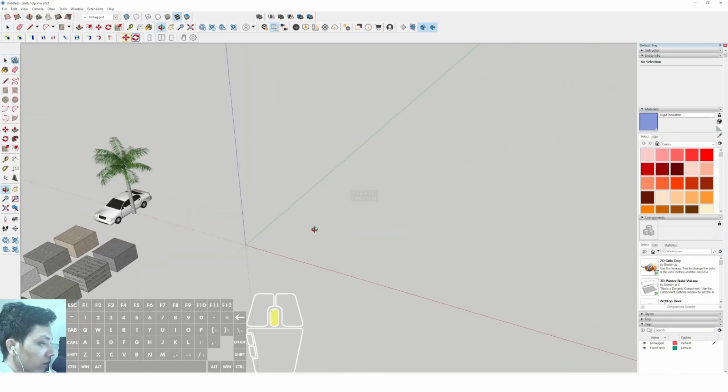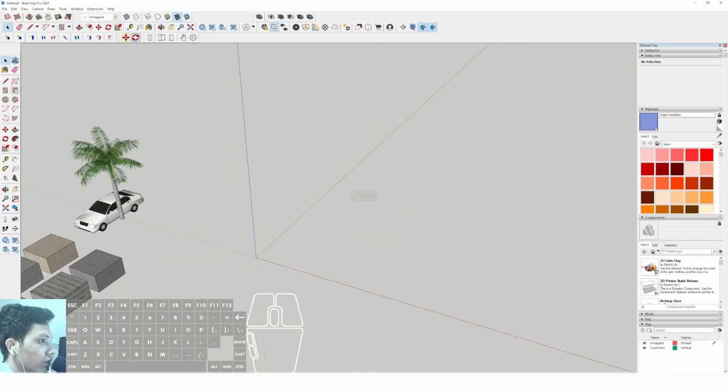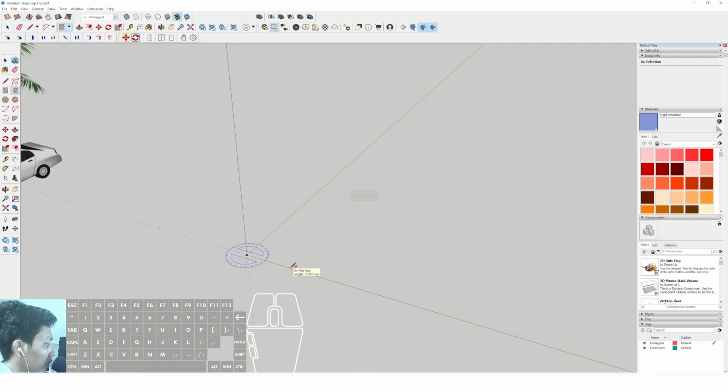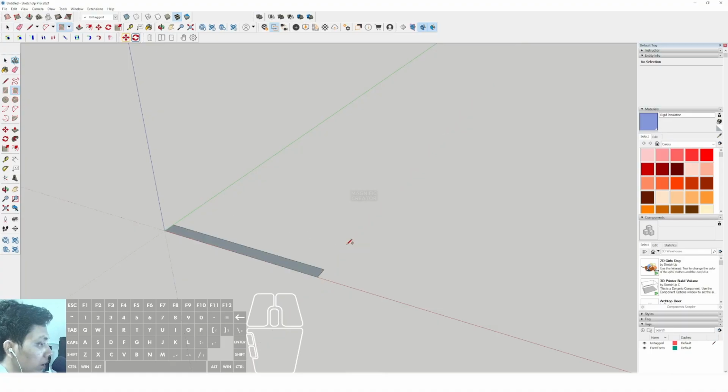This is about the technique of how to make a bay window in SketchUp. First of all, we can use the rotate rectangle. Click from the position, then we can type around 2 meter. Enter and move it to the behind, and then we can type 150 millimeter.